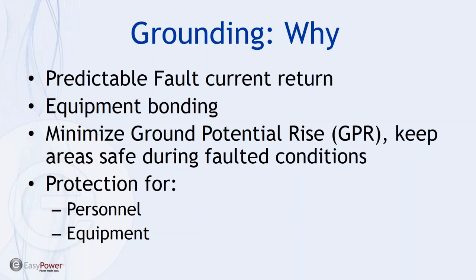Low resistance ground grids, more copper in the ground or a well designed ground grid, can help keep local ground potential rise lower, which can help with step and touch safety, but it also helps provide a low resistance path for voltage surges such as lightning and transients.